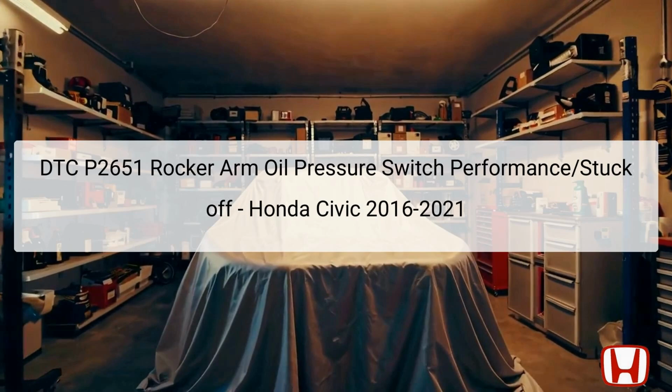The diagnostic trouble code DTC P2651 indicates that the rocker arm oil pressure switch is experiencing performance issues, specifically being stuck off. This component plays a crucial role in the variable valve timing and lift electronic control (VTEC) system of the Honda Civic, helping to adjust the timing of the engine's intake and exhaust valves for optimal performance and efficiency.